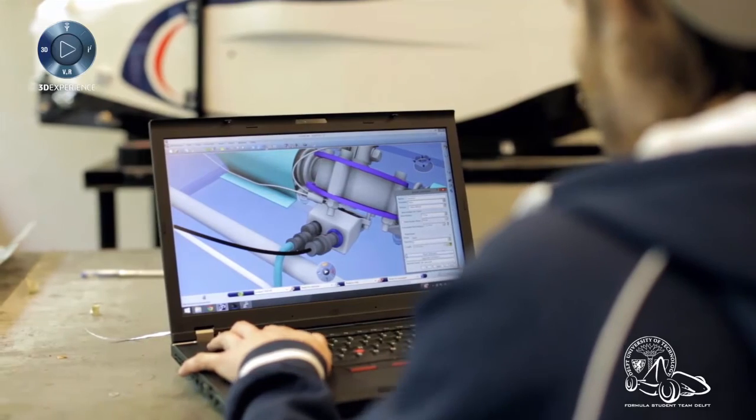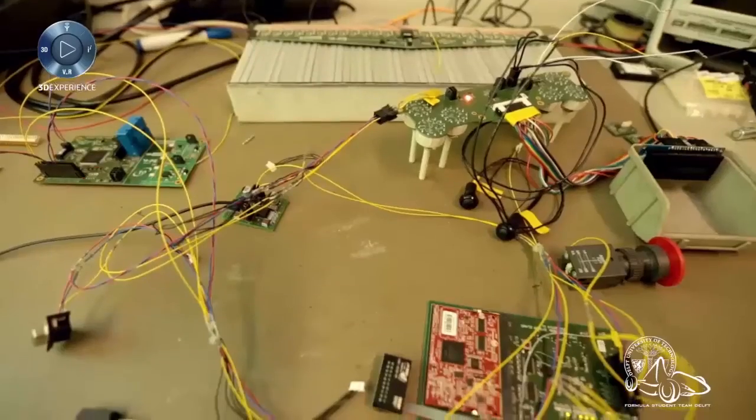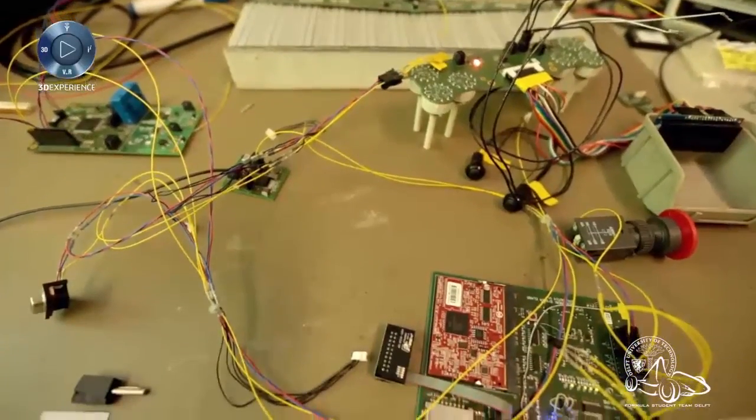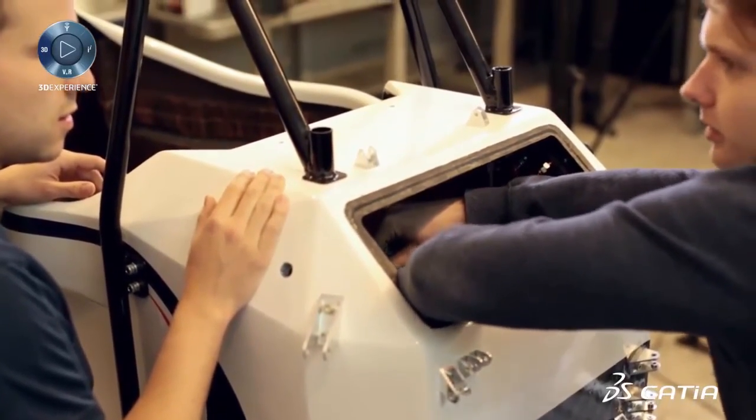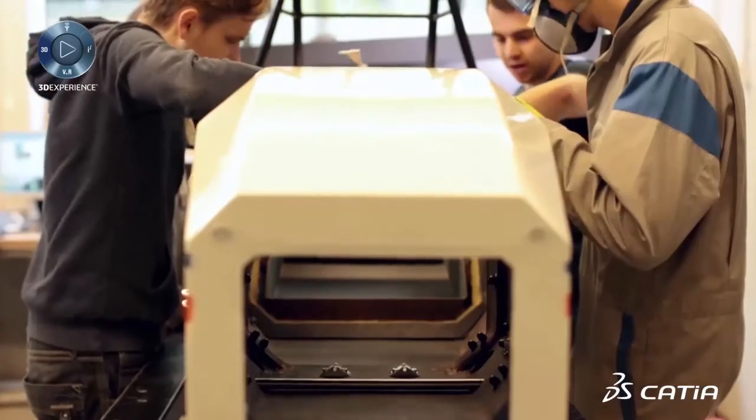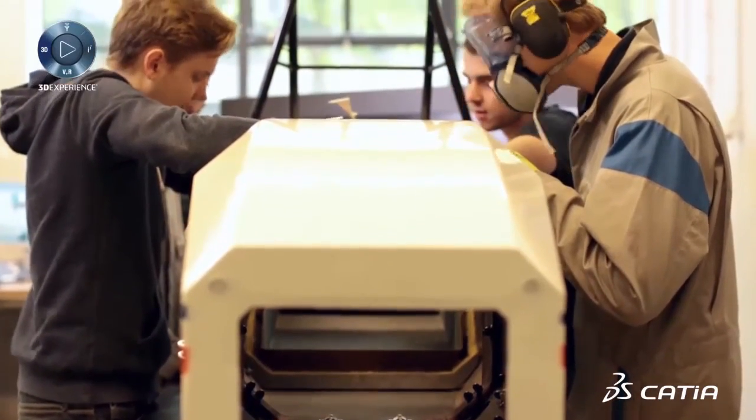We used flattening to design the drawings for the wiring harness, which we printed full scale, which was a big help during production. Then we calculated the length of the wires, and we used these during the production. We put them on the drawings. They were perfect in size, which meant we could really go quickly through the production.